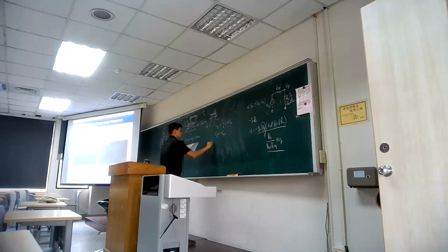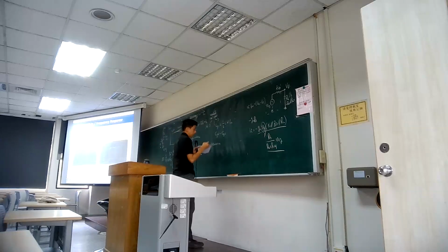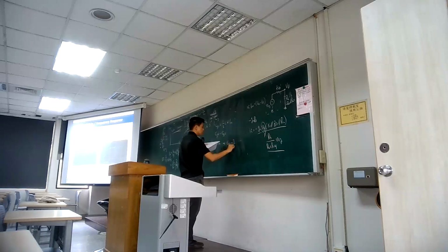you can consider, okay, I get additional drain induced charge distribution in which we get more charge along the source side. This then, there will be discharge in the drain side. So what happened here is there will be a redistribution behavior. So there will be CGS, which is around 2 thirds times